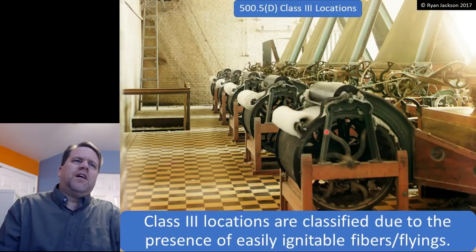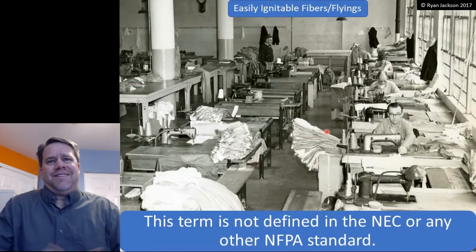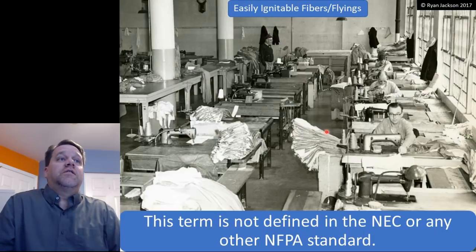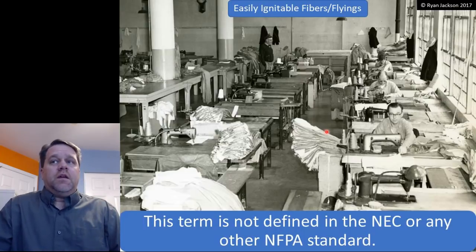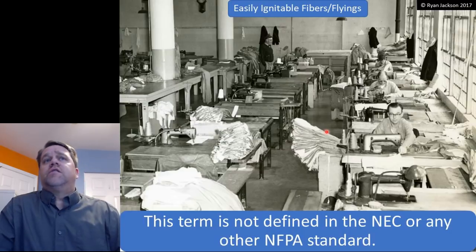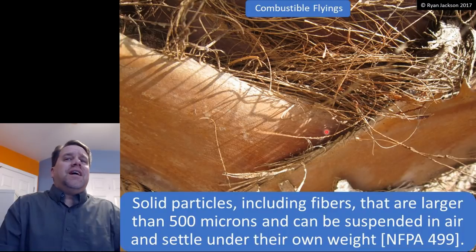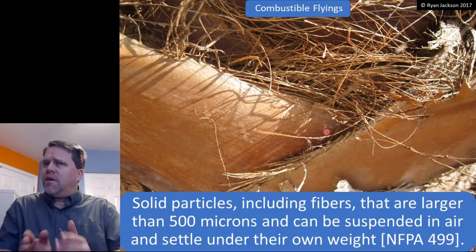And the problem with that phrase, what is an easily ignitable fiber or flying? Well, I don't know, because it's not defined. Seriously, it's not defined in the NEC. So if you have an easily ignitable fiber or flying, whatever that is, then it's a Class 3 location. It's not defined in any NFPA standard that I've been able to locate. I've looked in NFPA's glossary of terms, and it's not there either. In NFPA 499, it defines the phrase combustible flyings. It's not easily ignitable fibers or flyings, but I think that it's probably pretty much the same concept.